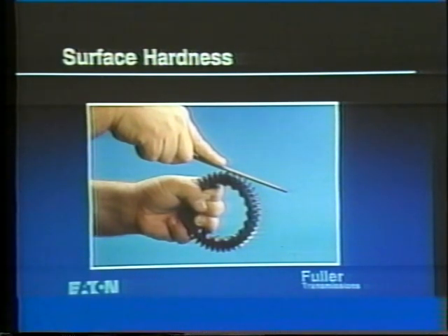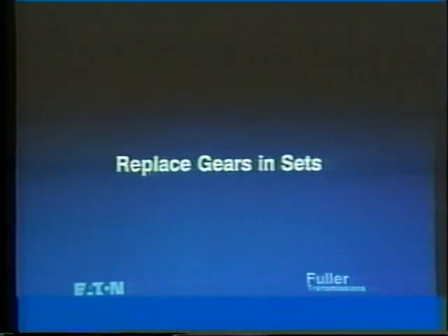Most parts which have failed from overheating will show discoloration. However, be sure to check other parts if a heat failure is found. The heat treat may have been drawn out of other pieces, although they may not discolor or show other visible signs of damage. When replacing a burned gear, always replace the mating gears even if they seem undamaged.